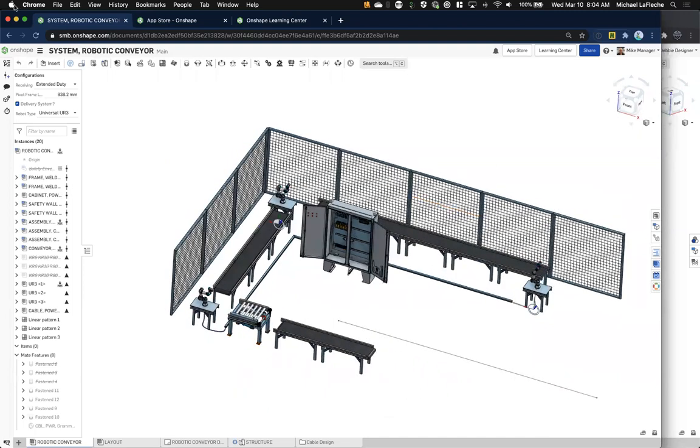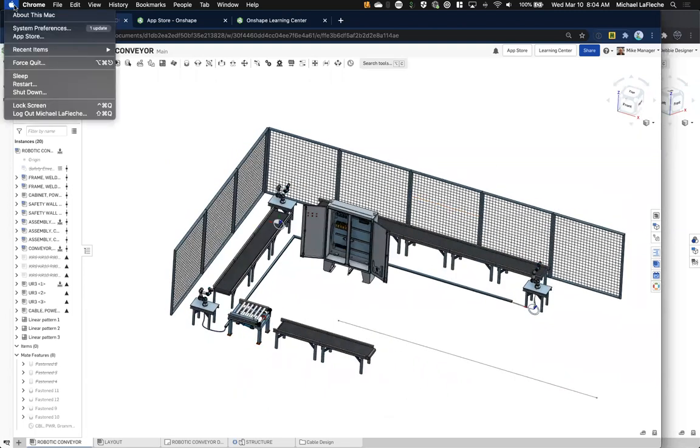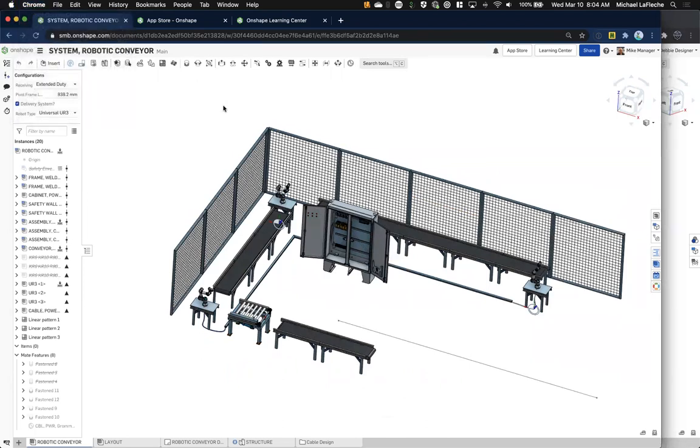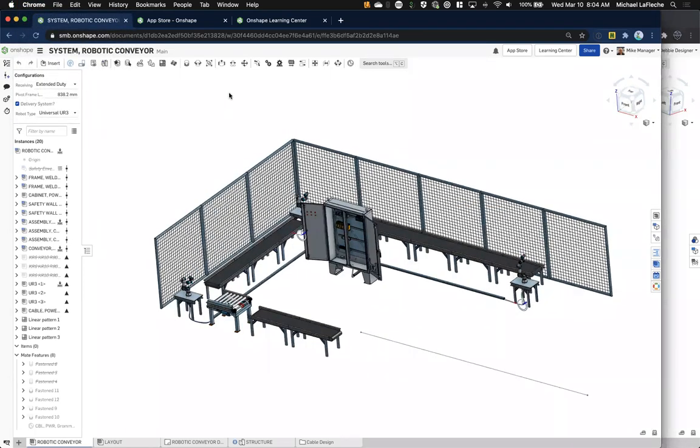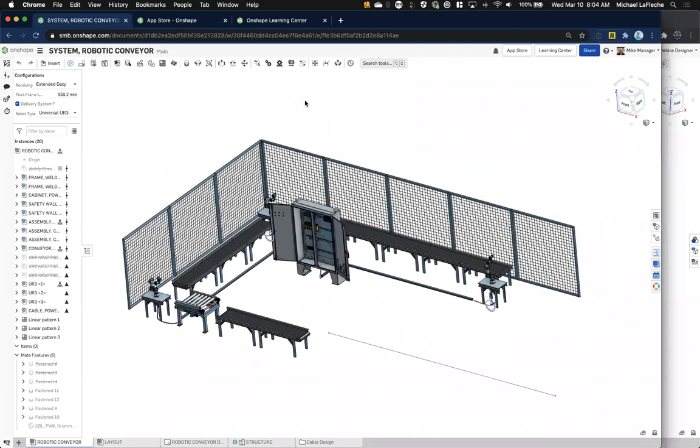So the most important thing, if you're working on large assemblies, is just to have some sort of graphics card on your computer, but it does not need to be the special graphics card that you need for a CAD workstation. It can be any, like for video games or something, it'll be fine. So that's really the only thing you have to worry about. Bring a computer that's modern, has a web browser with a small internet connection, and that's it.